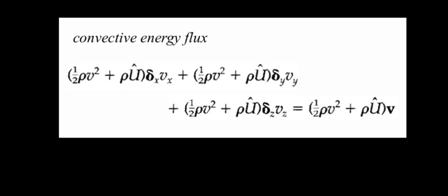Expanding this and considering the convective term derived earlier, we can see the combined energy flux accounts for energy carried by bulk motion of the fluid. This includes the internal energy and kinetic energy as well as the work done by pressure forces, represented by terms involving the velocity components Vx, Vy, Vz and pressure P. Energy transfer due to viscous stresses.